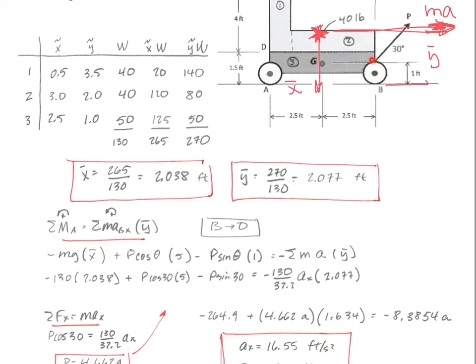It'll have a cosine component going this way, and this is the lever arm for that. And that's what these two are all about. Now the mass times acceleration vector is going in this direction, and what I defined as positive was the counterclockwise direction, which means that this mass times acceleration vector is in the clockwise direction, which means that it has to be negative over there.